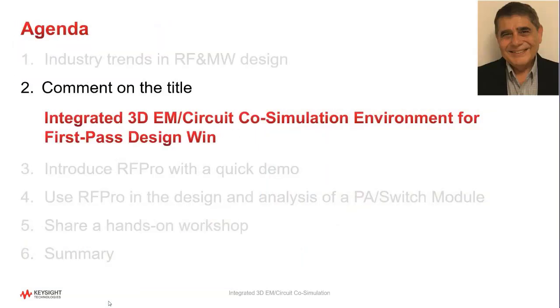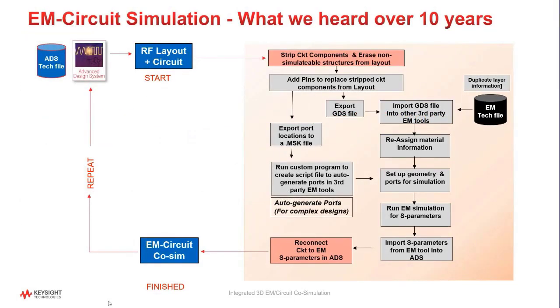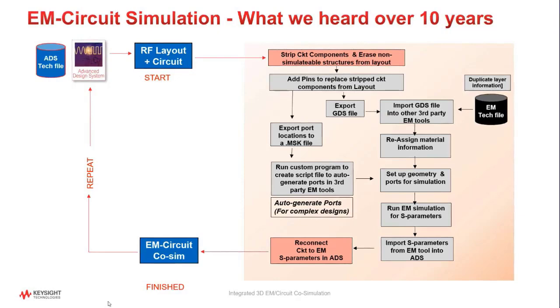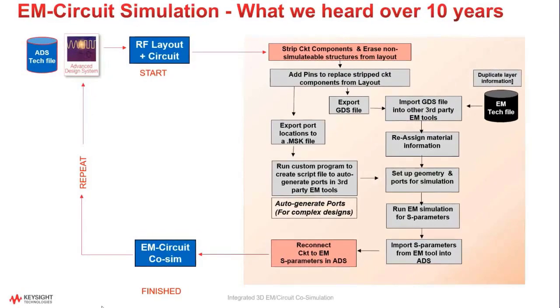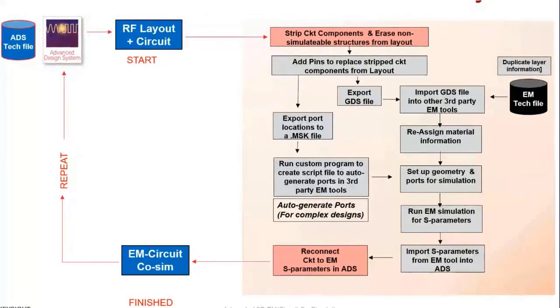Now I want to explain why I chose this title for the webinar, Integrated 3D EM-Circuit Co-Simulation Environment for First Pass Design Win. You see, in the past, 3D EM simulation was performed as a separate task, disconnected from the design flow. For example, and most of you might have experienced this flow, first, the design is exported to some EM simulation tool. All SMD components and active devices are stripped off and removed from the layout, and the remaining portion to be simulated must be cookie cut out to be analyzed by the EM simulator.